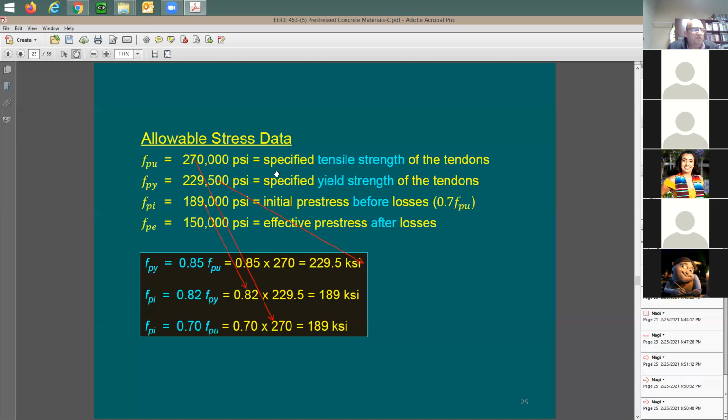It's not good. So you're going to say, well, maybe I'd like to bring it close to FPY. You're going to say, yeah, this is good. Let's put here tension, not just 189. If the cable is able to take more tension, I'm going to go here to 229. What's the benefit of doing this? You're going to be reducing the amount of strands needed. Instead of putting, let's say, 7 strands, when you run the same numbers for the previous example or homework, maybe you're going to end up with 6 strands. So there's going to be less cost. So you'd like to put higher strength material, and you'd like to push it close to FPY so that you reduce the number of strands. You'd like to save money in this case.